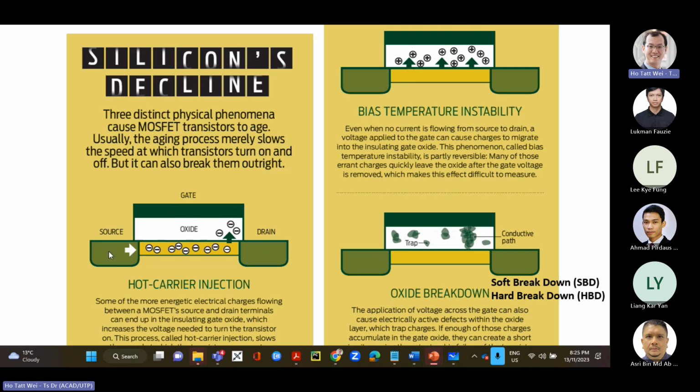So what happens if you actually have a positive voltage here? Let's say this is an NMOS transistor, N dope, P dope here. Sorry, let's say it's a PMOS transistor, P dope, N dope here, so you pull up electrons here, okay? If you have a positive voltage here, then the electrons will be attracted up this way, right? But if some of the electrons actually get stuck here, these electrons will reduce the effective positive voltage here. How is that, right?